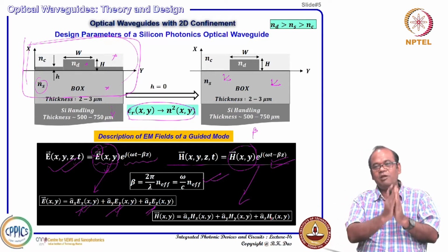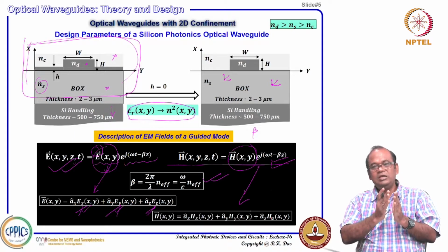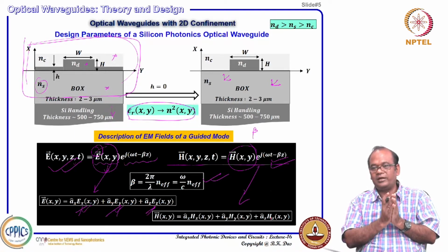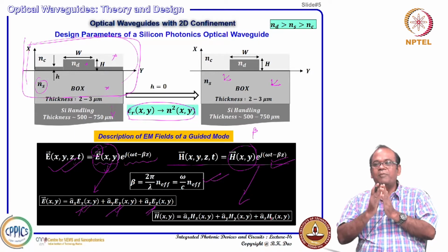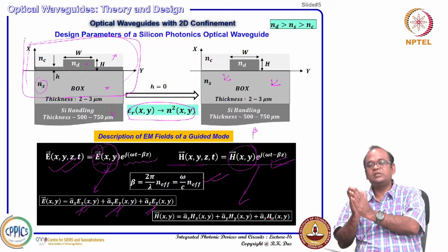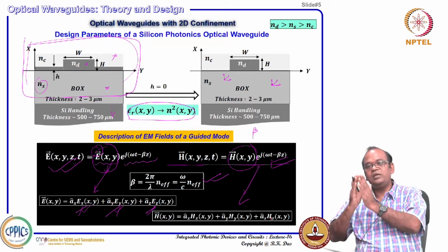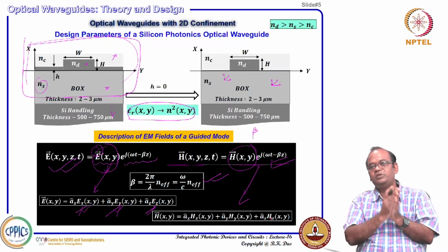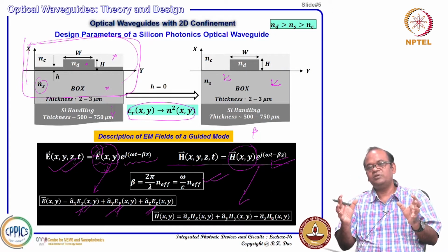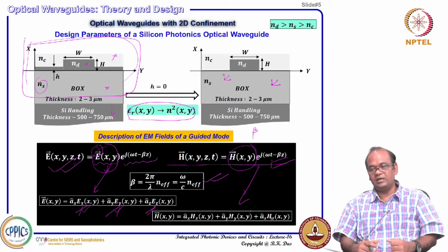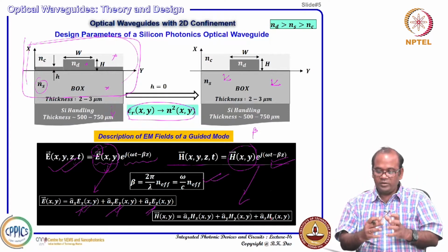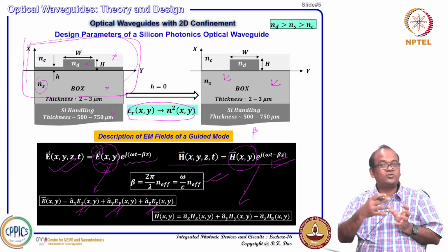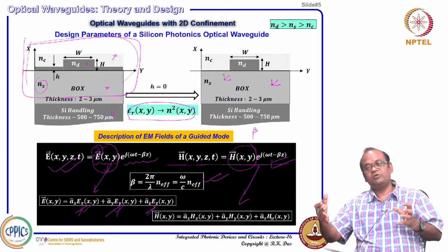In the case of TE mode, we considered only the Ey component for the electric field. And in the case of TM polarization, TM mode, we considered only the Hy component of the magnetic field. That is how we could decompose TE and TM easily, and analyze them independently, individually. That was consistent with Maxwell's equations for propagating energy or carrying energy in the 1D waveguide.